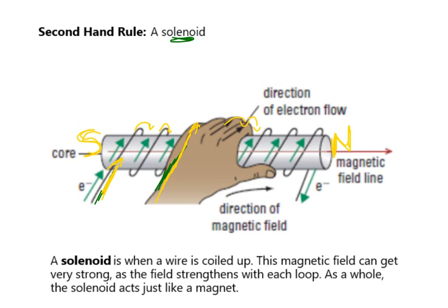Based on this orientation, if the electrons do go around like this, that should make this guy the north pole because that's where my thumb is. I just have to make sure that I set the electrons up properly. Okay, so you know how I have two different ways that I can hook these up? I could either go black here and red here, or I can flip it around. If I want electron flow, electrons go from the negative to the positive. So I'm going to set up the negatives starting here to the positives ending here.